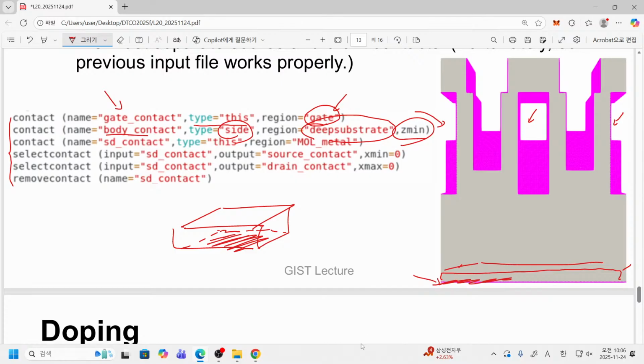And here we have one interesting part, source drain contact. If source and drain are connected to each other, then we cannot have the real current. When you make the same potential for source and drain, if they are equipotential, then we cannot have any kind of drain current. So we must separate them. How did Mr. Zhang make it? Oh, I think that is quite clever.